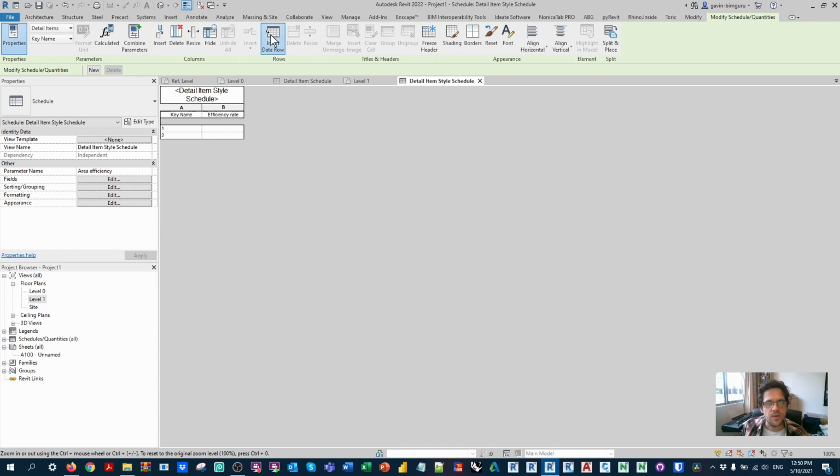I'm going to insert some rows, and in this case, let's call this apartment. Let's call this circulation and core. And in this case, our GFA efficiency, or I guess our yield, in this case on apartments, is maybe something like 80%. So I'm going to make this number 0.8. Circulation and core, I'm going to make 0 in this case, because they don't have any associated sellable area. So I guess instead of GFA, I'm looking more at NLA at this point. You could do different sorts of efficiencies for GFA. So for example, if you were doing GFA, your circulation would contribute towards that to some degree.